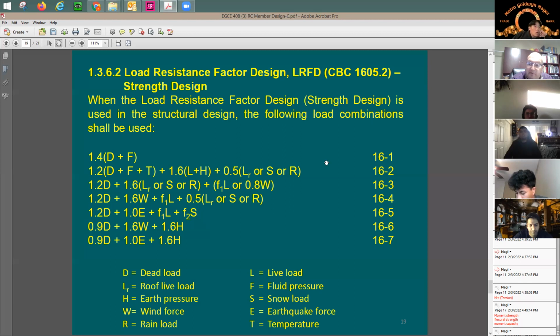He's going to put a little bit of mortar. All of a sudden, the weight is larger than what I designed for. How about the mechanical ducts? Can you confirm exactly what mechanical ducts are going to be installed below the slab? I'm going to say no, not really. You'd never know what they're going to install. This is why I have some uncertainty about the dead load.